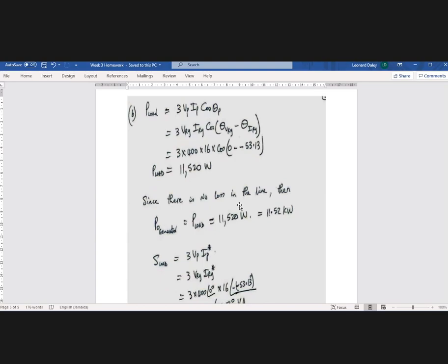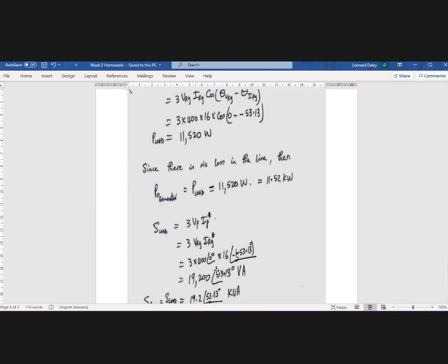So up here, power is equal to S cos theta P, right? But S is the VI conjugate. But at the top, S is VI without the conjugate. So the angles are here, so we still account for the angles. When I write it like this, you can see exactly the correct angle for S when we do the VI conjugate.